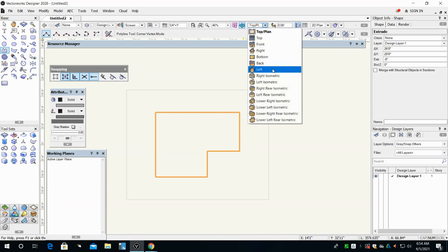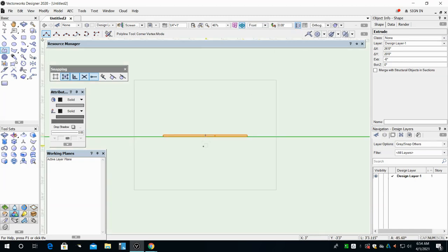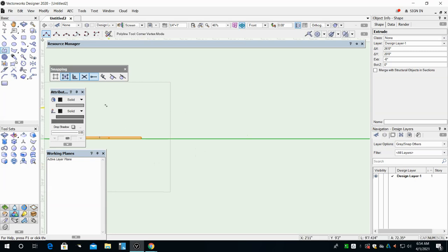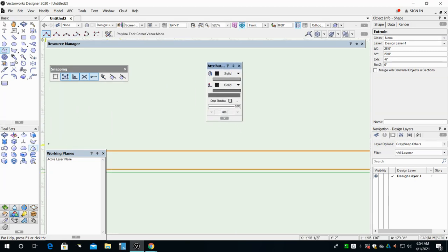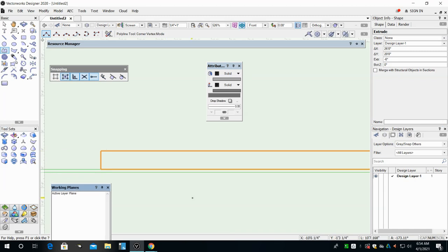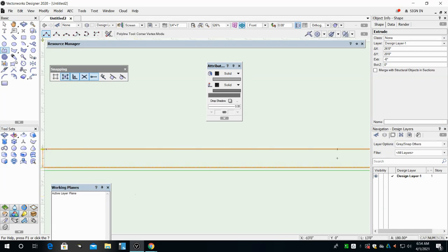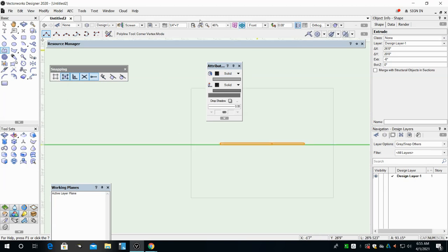And here's why we wanted that extruded at negative 6 inches. If you look over here at my ruler, you'll see now that the top of my slab is right at 0. The concrete slab goes down 6 inches. I have a 1-inch thick layer for my grass material. And when I build the walls, they're going to be going from 0 up for this project.